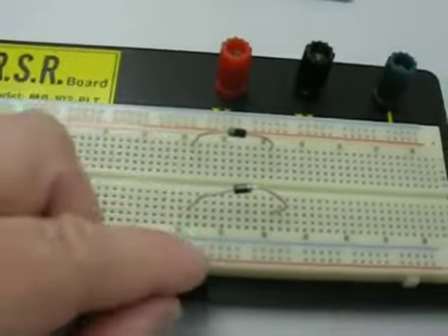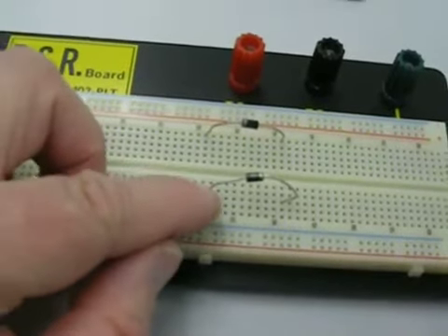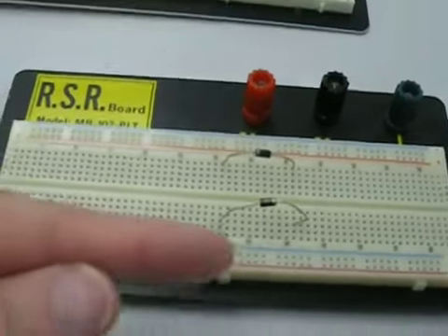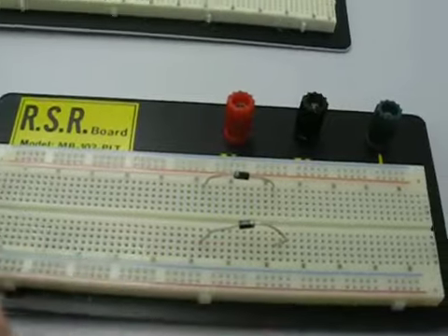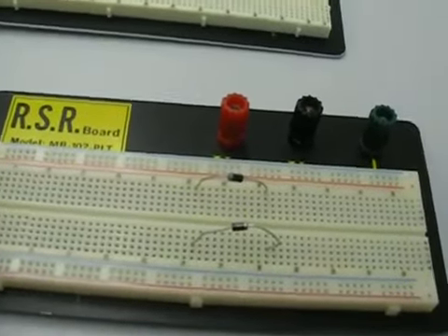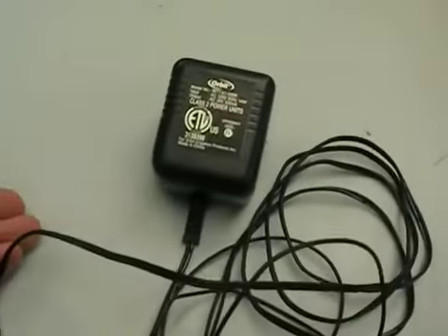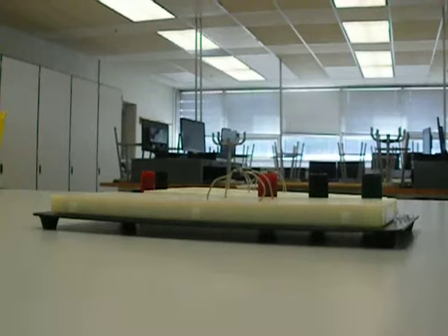On the other side of this divider, I plugged another diode in, but with the band facing the opposite direction. That's really key for this, because we're going to set up different rectifier networks. We're going to start with the half wave. So let's get that half wave. I told you we need this power adapter, so I need to plug that power adapter in.